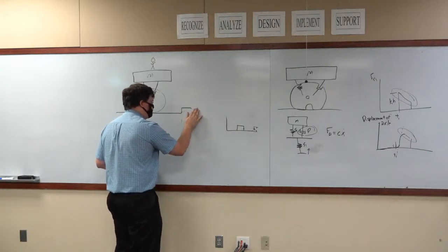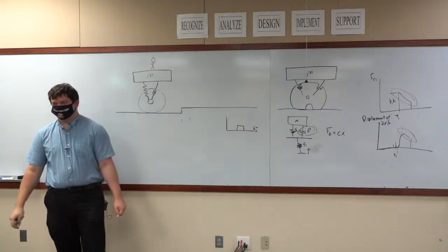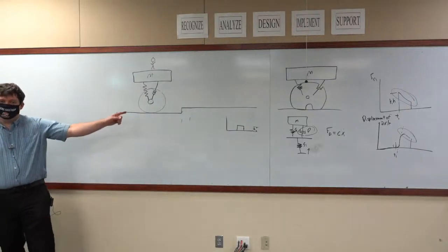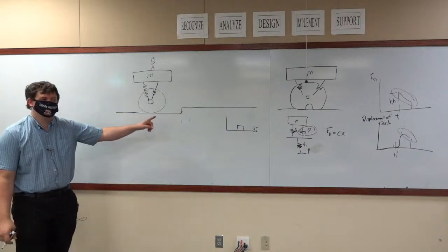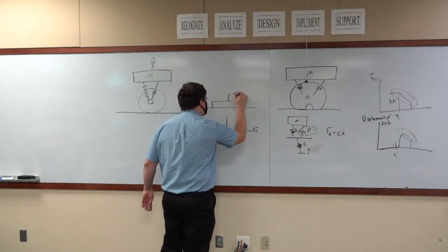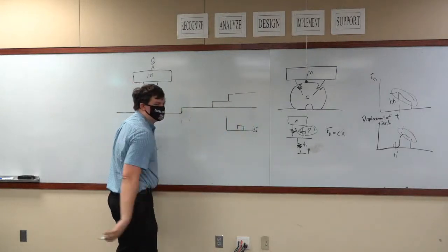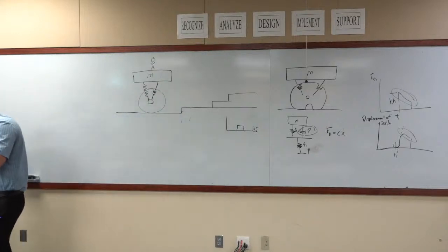Okay? Bad suspension. This isn't a bump. This is a curb, and that ground is flat afterwards. You never move upward. Is that good suspension or a bad suspension? That's bad because it means the next time you hit a bump and the next time, pretty soon your vehicle is going to be running into it. Your suspension just keeps compressing until your car runs into a mountain.